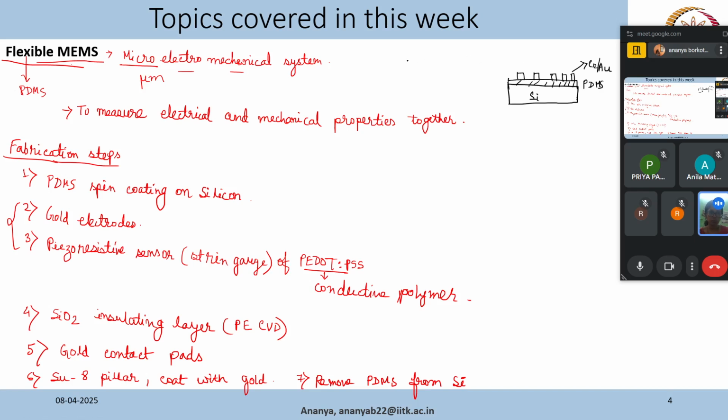Okay, so this will be something like this. Suppose we have this PDMS and a gold layer on top of it, and then say we have photoresist here and photoresist here. Okay, we will do etching. The portion of the gold that is below the photoresist will not get etched, because the etching will be, say, directional.